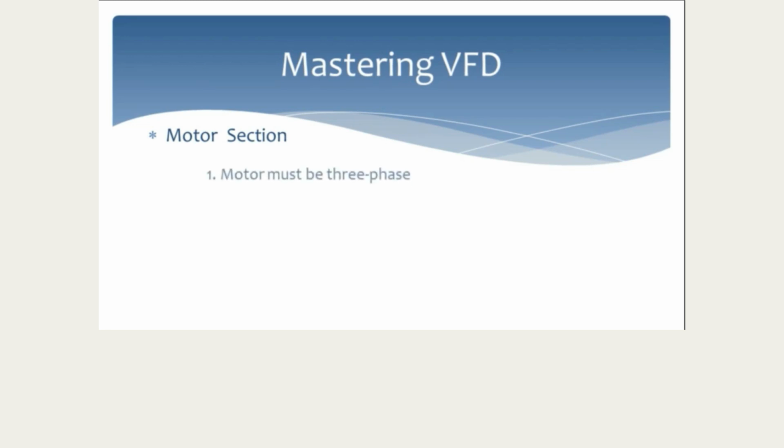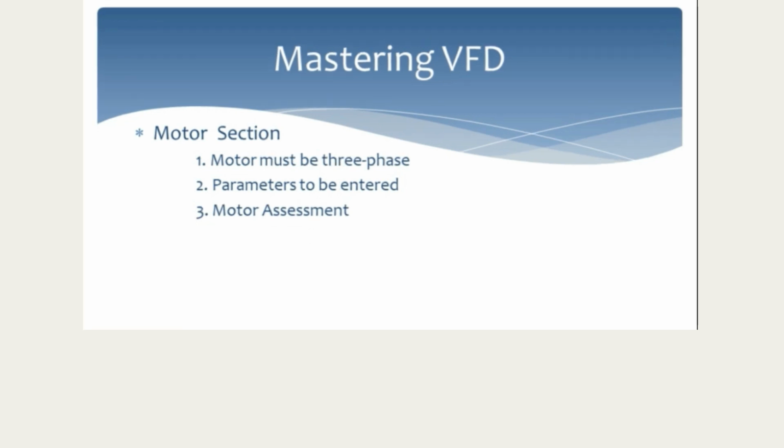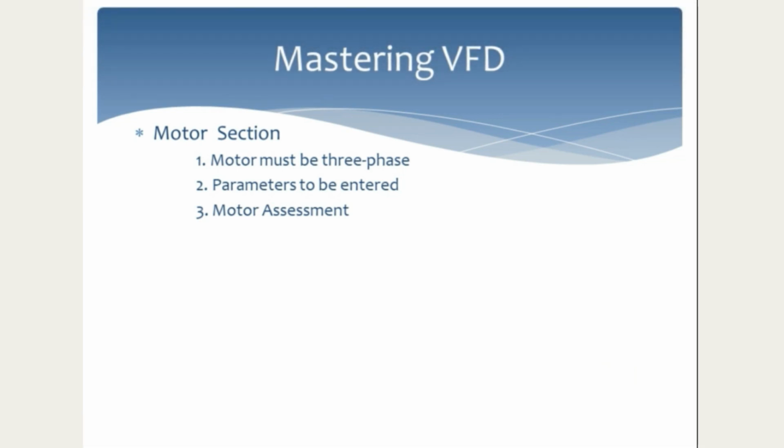There are three things we need to know about the motor for VFD. Number one, it should be a three-phase motor. Second, the parameters to be entered in the VFD. And last, motor assessment.